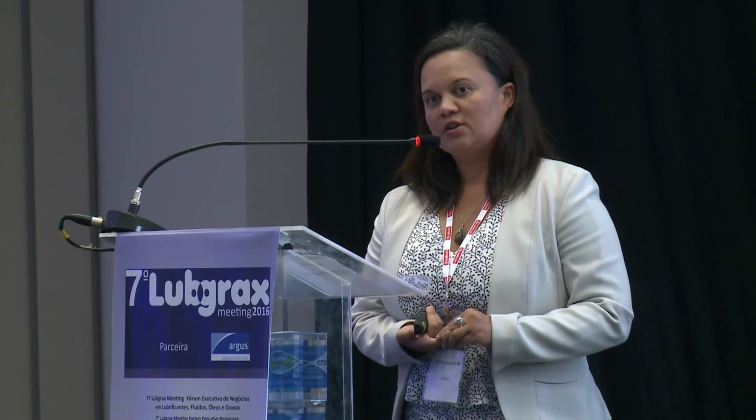Right, I did introduce the NYNAS range this morning, so I won't spend too much time on it, but just to say that when we started creating these products, we focused primarily on the viscosity and the aniline point, so we matched them up with the existing solvent-neutral oils. You will, of course, get the benefit of good low-temperature performance. Compared to Group 1, you will have the challenge of maybe a slightly lower viscosity index, and you might also have a challenge of a slightly lower flash point. However, this is not always required in all applications.